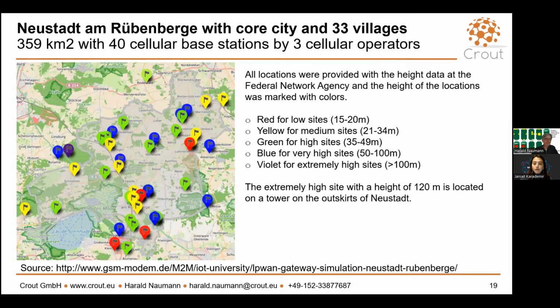If you take 10% of 3,600 seconds, which means 1 hour, then we have 360 seconds for communication for all the devices. If we have 5,000 devices and would like to make an acknowledgement, then we have only 360 seconds left. That means upload is much nicer with LoRaWAN than download. So if you would like to work with an acknowledgement with LoRaWAN, you will run into trouble. It will not work. That is the limitation in the unlicensed band: you do not have enough capacity for the download task.